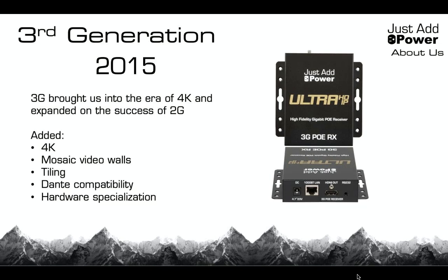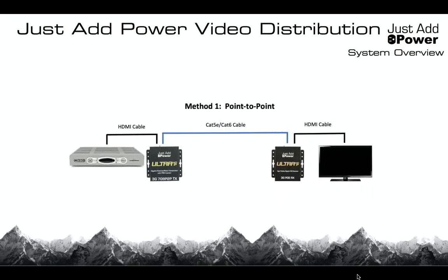They don't have to buy all new hardware and start all over again like they would have to do with a matrix switch. In fact, we can take the new 4K content, down convert it to 1080p or 720p or something like that, and send it back through the system to older devices, just by buying an additional receiver to do that. So all the new 4K TVs get their glorious 4K content, but the old TVs can now also watch that 4K content in a resolution that they can handle. So it's very easy to upgrade the system over time.